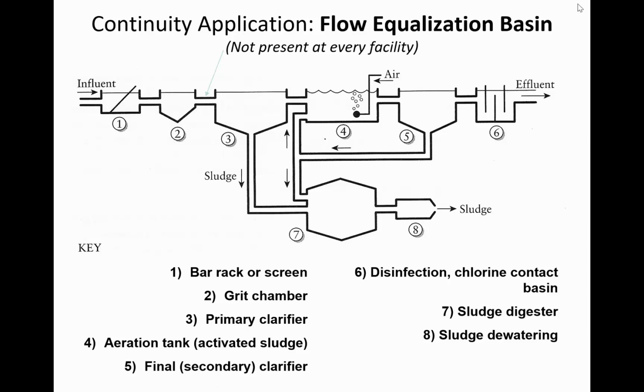And so sewage water comes into this treatment plant, and the first stage is to screen out large particles, like sometimes debris will get down into the sewer, like toys and diamond rings and stuff like that. And so this first bar rack here at 1 is just to screen out the very largest particles.